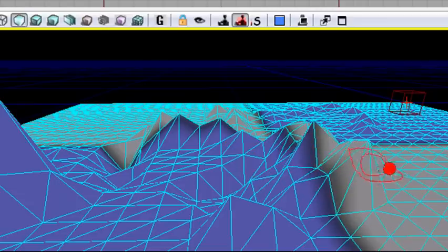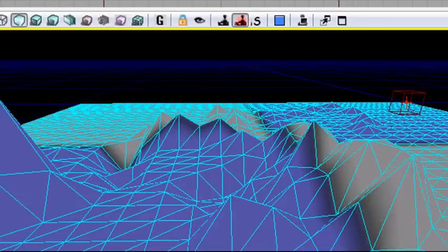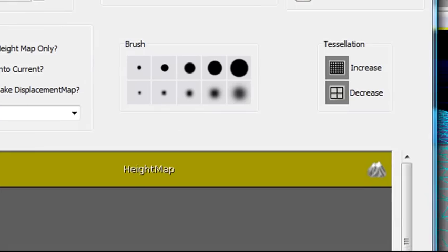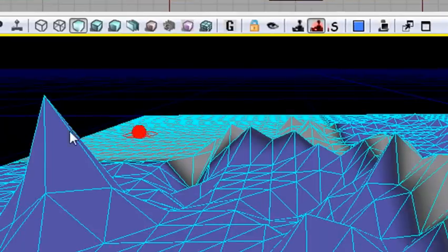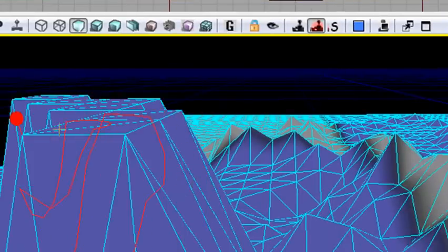And so we're now kind of trying to build something up. So let's look at some other features of the control panel. So here's the terrain editor. Now what I can do right here is actually flatten the mountain out at its regular height. So I come along here, I'm going to roll over my flatten button, hit the control key and start drawing, and see it flattens everything out.